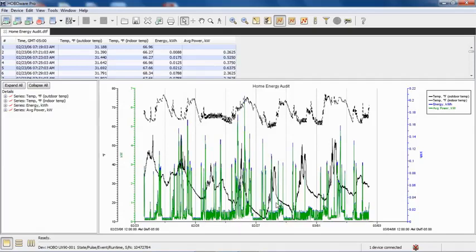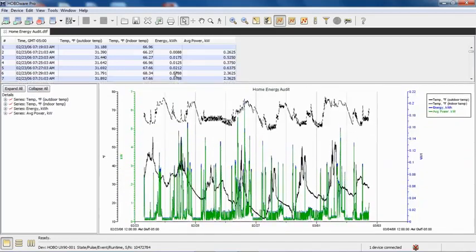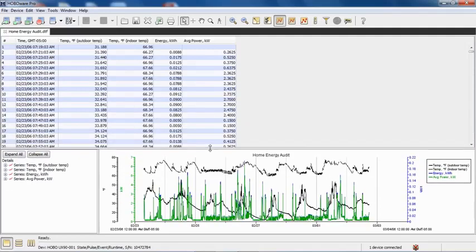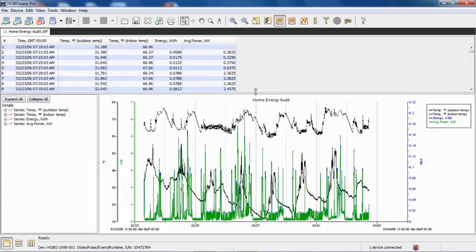So there is my data. And again, several weeks of data. There's my data table. This logger was logging every 2 minutes, which is pretty fast for energy. And if you recall, we talked about setting a longer interval to get more pulses. So you can see that our scaled data is very small. The kilowatt hours per 2-minute interval is an extremely small number. And again, here's our average power per interval in kilowatts, based on how many intervals there are in an hour.